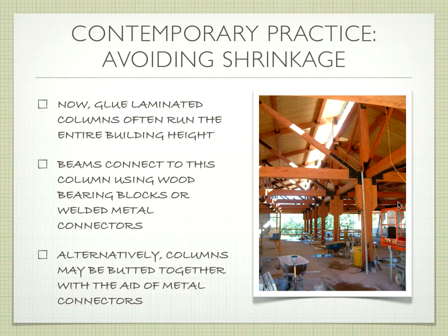Is that one they used to use, like a 2x6, like a tongue and groove type of wood? Right, exactly. It's like a tongue and groove. Sometimes it's even thicker than a 2x6, and then you can use plywood on top of that as your flooring material. But the plywood itself isn't thick enough to classify for the same fire rating.